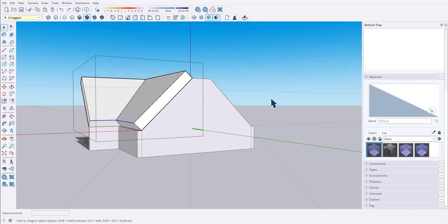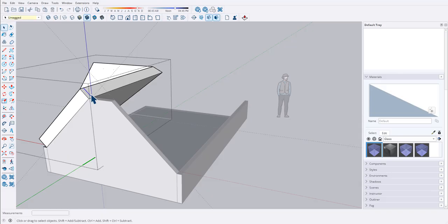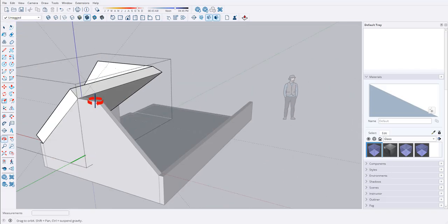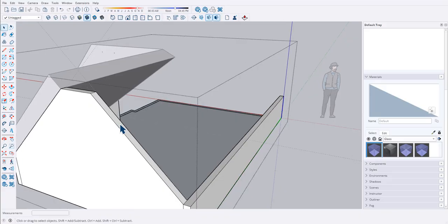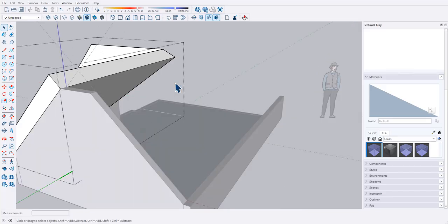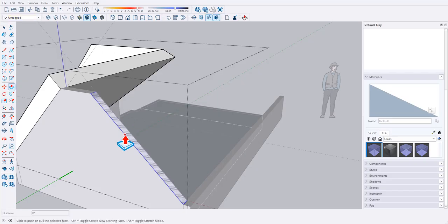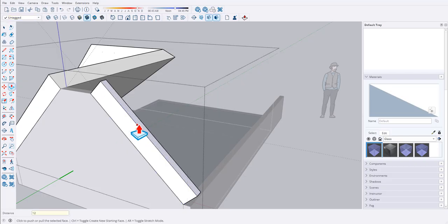So I'm gonna go over here now. I'm cleaning up as I go. I'm gonna select this rectangle, edit, copy, get out of the walls, go into this ceiling, edit, paste in place. P for push pull, and I'm gonna type in 12 as well.